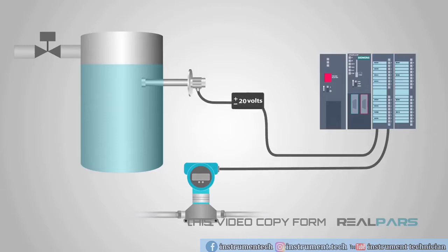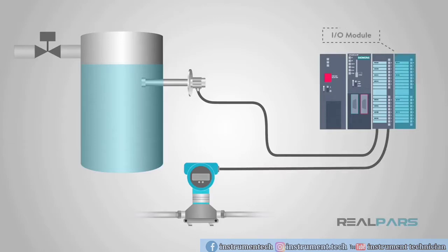Voltage signals in the range of plus or minus 20 volts or so, and current signals in milliamps are commonly used as analog inputs to PLCs. Every PLC manufacturer has I/O modules to deal with these kinds of signals, along with other, more specialized modules. The simplest of these types is the voltage input, so we'll tackle it first.